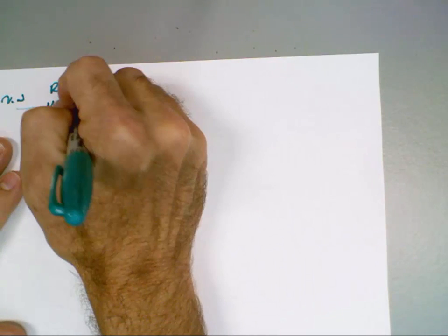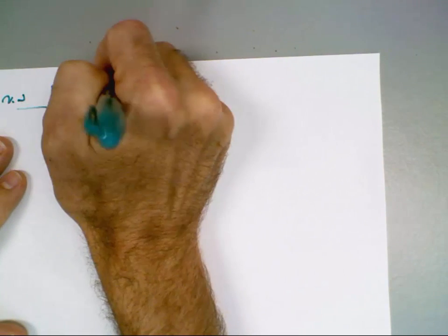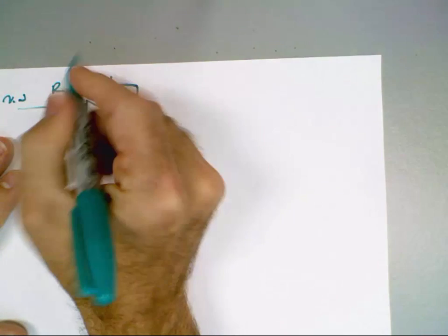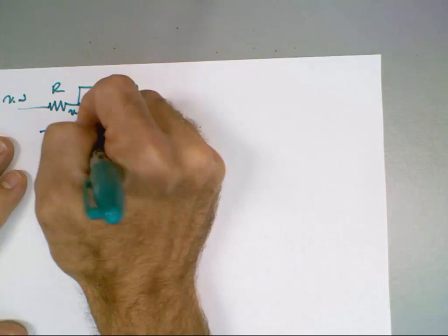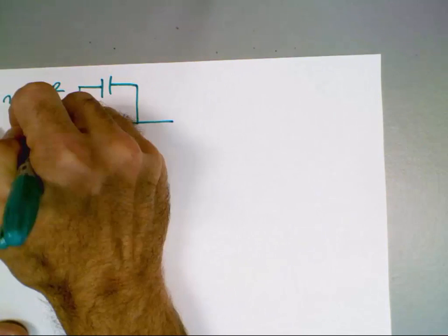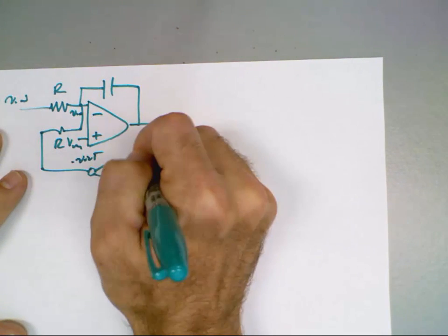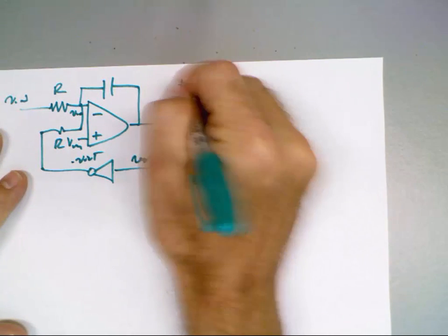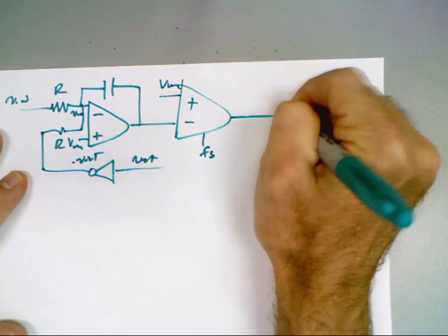So what we have is our input, Vin. Practically, this is the way a lot of the modulators are made. Then we have our feedback resistor R, the common mode, the DAC with the inversion, minus Vout. Then we have this going into the minus input, plus VCM. This is our clock frequency. This is our output.